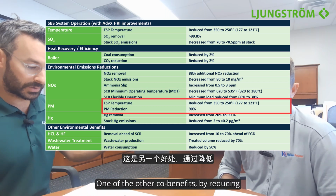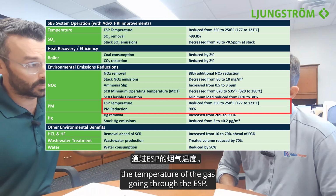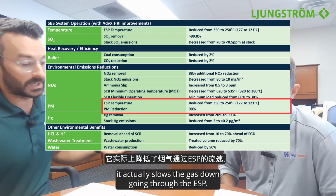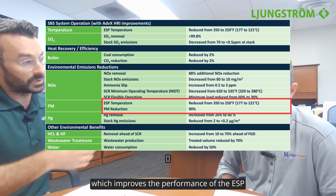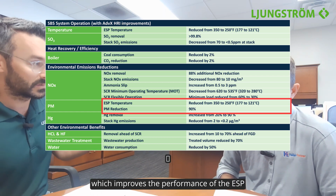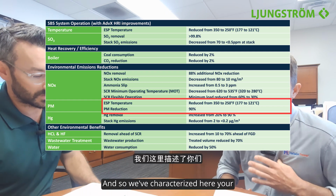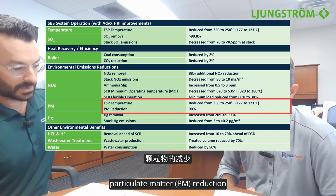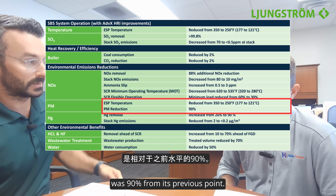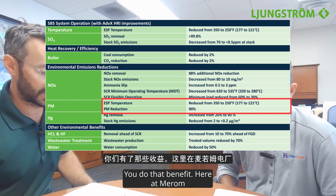One of the other co-benefits by reducing the temperature of the gas going through the ESP, it actually slows the gas down going through the ESP, which improves the performance of the ESP as it's a function of the velocity of the gas moving through. And so we've characterized here your particulate matter reduction was 90% from its previous point due to that benefit.